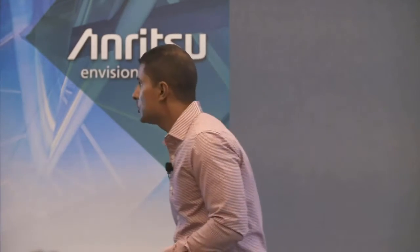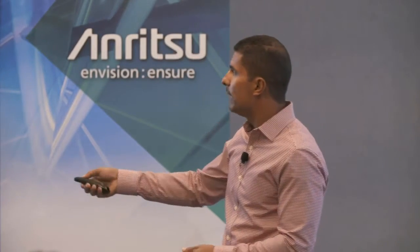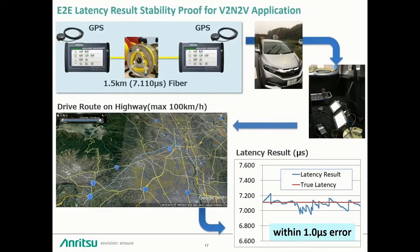We started off by taking 2 of our network devices, or 2 of our network testers. We connected them with a given amount of fiber because we know the speed of light. We know exactly how long it's supposed to take to go over that fiber. We use that as our reference point. We took our measurement of that 1.5 kilometers, and the reference is supposed to be 7.11 microseconds.